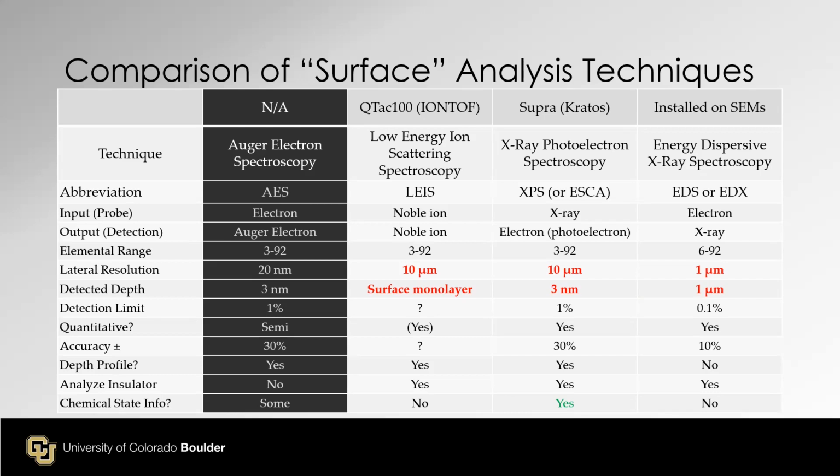Okay. At the end, EDS or EDX, electrons in, X-ray out. It works okay for 6, carbon, and higher, but for quantitative analysis, it is typically believed to be sodium and above. The interaction volume in the XY dimension is about 1 micrometer, and the same for depth.